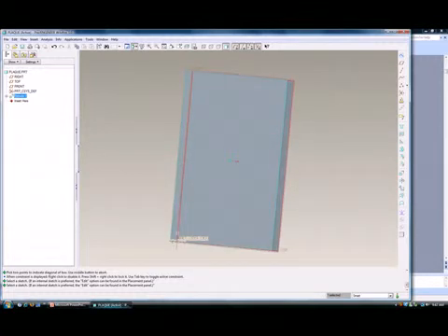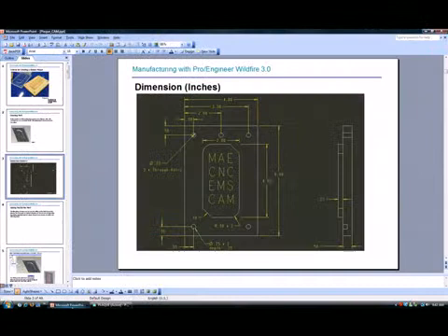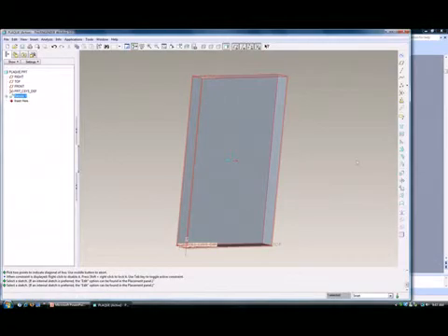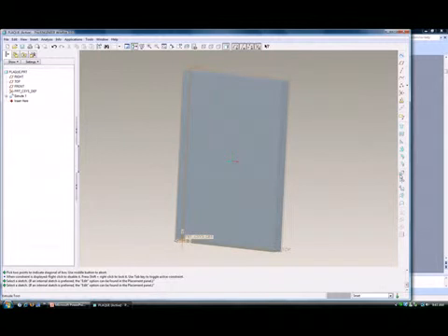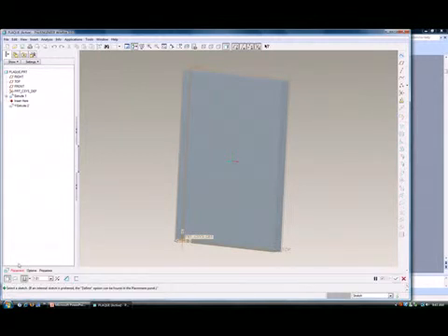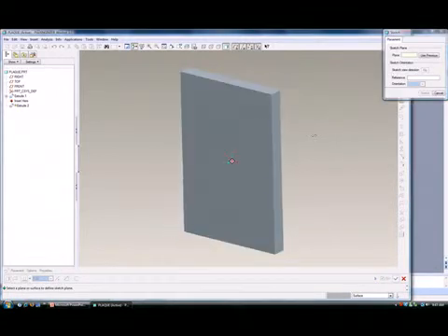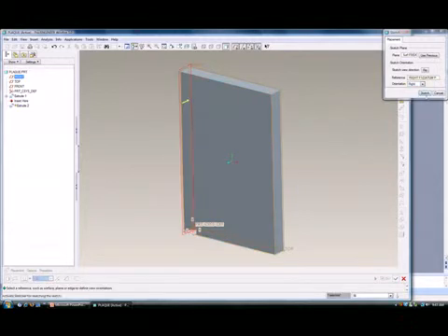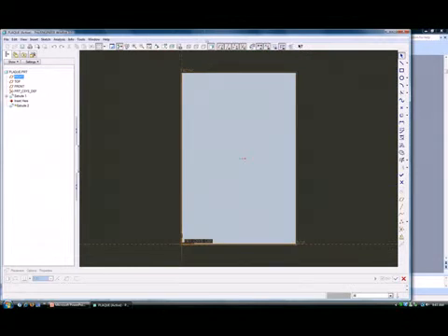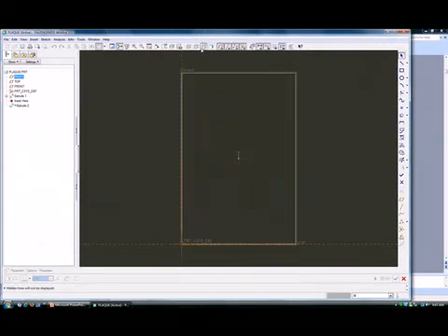The second thing I will do is extrude this island. I call it the island portion or the center portion here. Again, go back to Pro E and use the extrude button. Click extrude, click placement, and then define again. Now we are trying to extrude it from this surface. So we will click on this surface and hit sketch. You can always change the display view using these buttons here. I would like to use the hidden wireframe view to draw the island here.